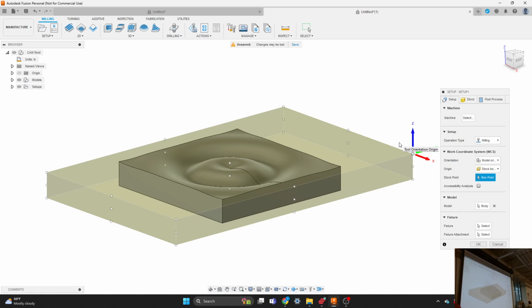instead of model orientation, click on model orientation and say Z-axis and X-plane, or either one of those first. There you go. And now, if you pick that surface that's between your blue and your red axis, or spin around so you're looking at the underside of your model. There you go, that one. Yeah. There we go. Now your Z is pointed up. Okay, cool. Now you can change that to 1 or 2 or whatever you want it to be. Okay, thank you.